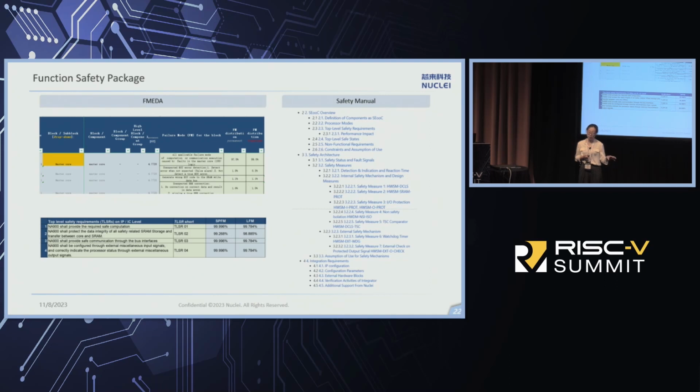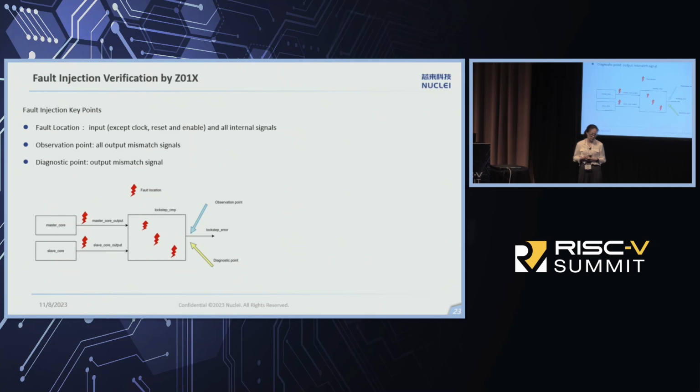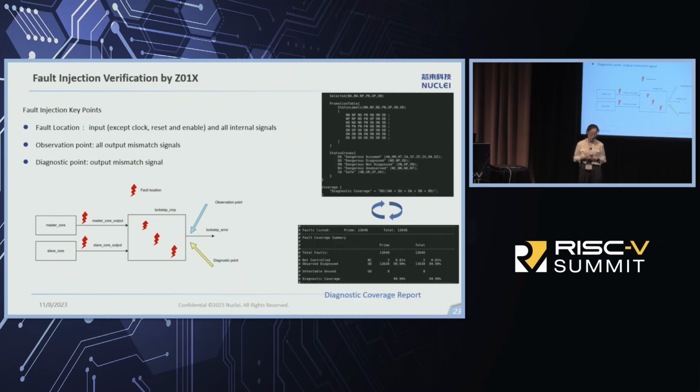We have done the FMEDA report on very detailed modules. And the safety manual includes the SoC safety architecture and also integration for the SoC. One comment here: we use ZOIX to do the fault injection verification. It helps us easily define the fault locations and also make observation points and diagnostic points. It can also automatically collect the coverage.